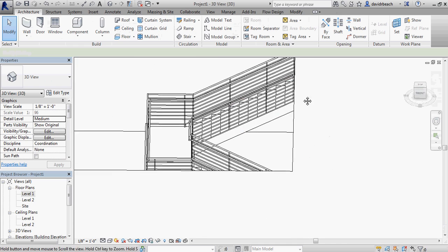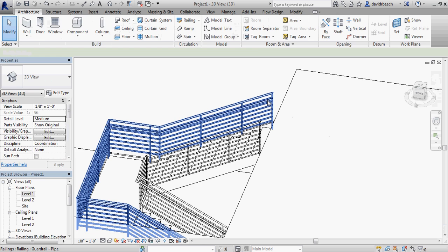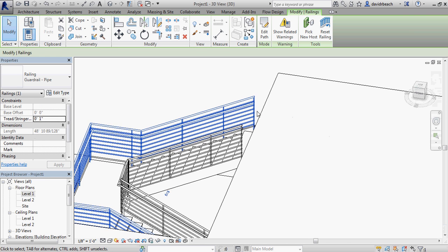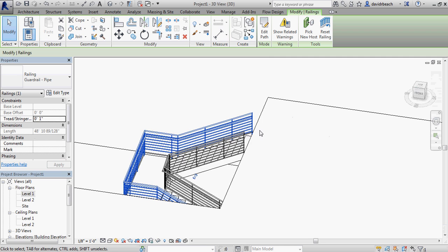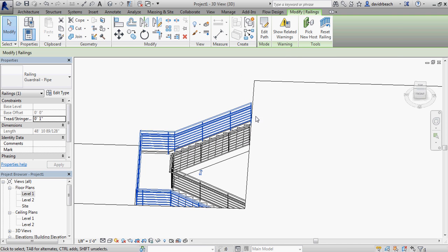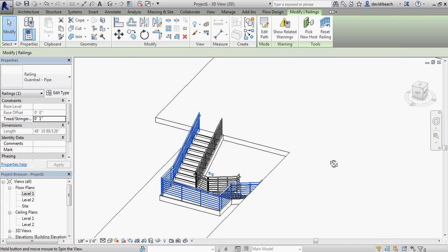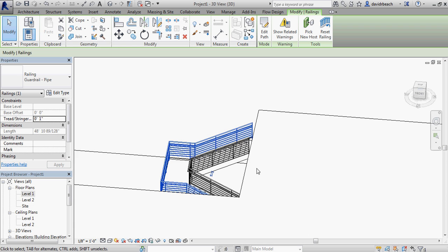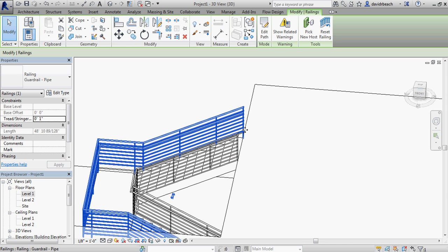Then up at the top, typically you would see an extension on this as well, 1 foot along the path. But the other thing that can work is continuing the handrail along a balcony edge or something like that. So if there was nothing else going on up here, I would need a 1 foot extension running parallel with the stair. But since I have a balcony, I can actually just begin to wrap that around. So that's going to be my design choice.